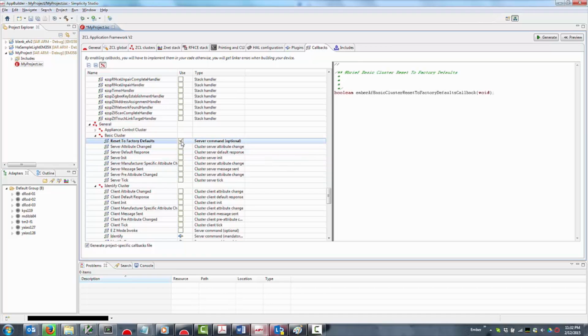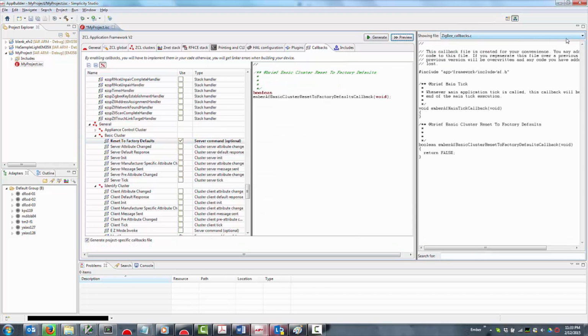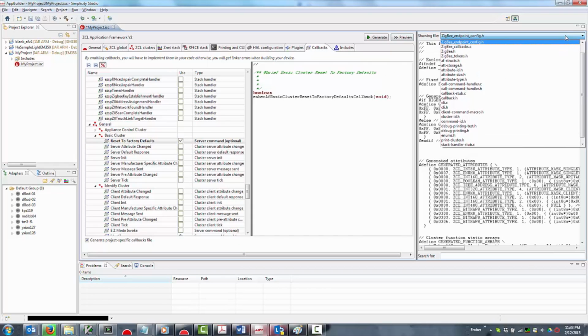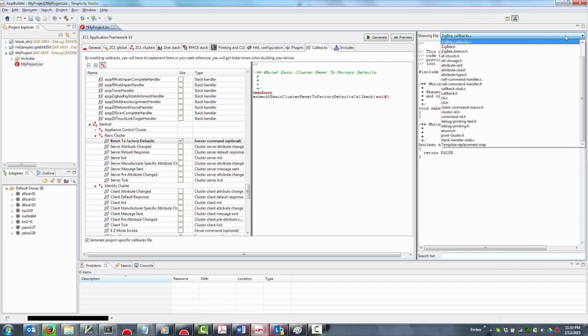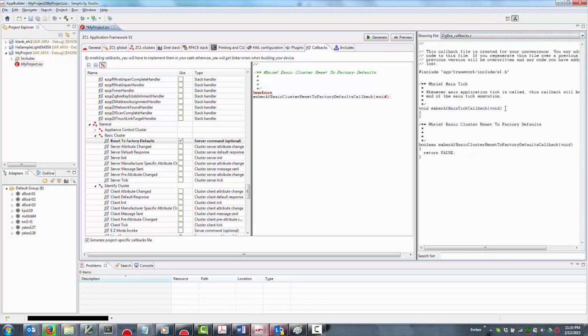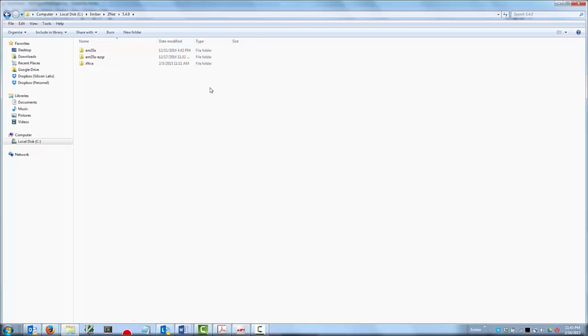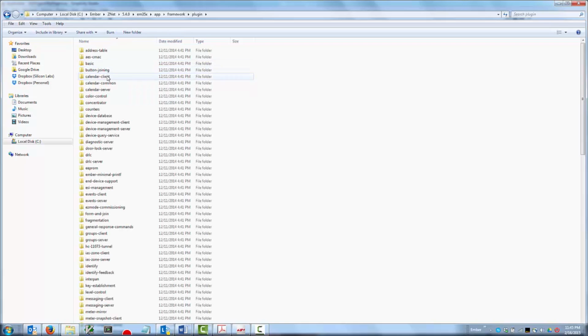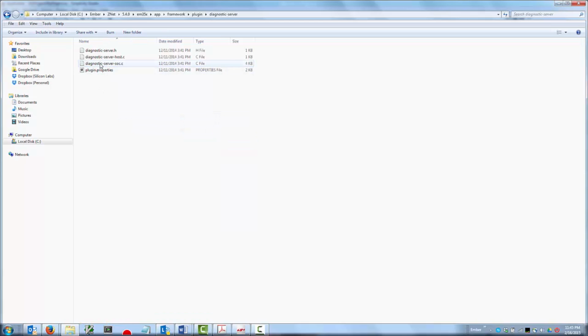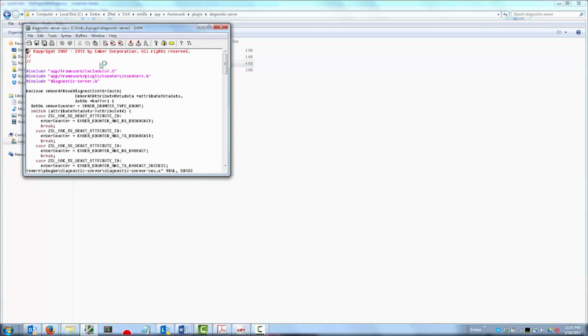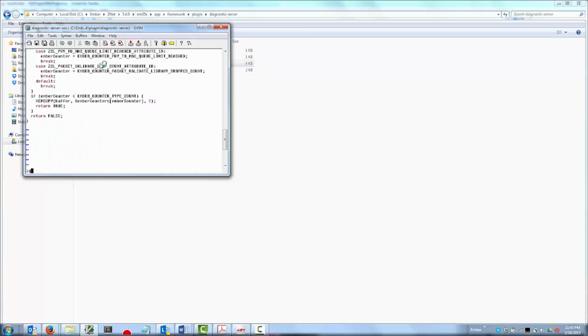Within the callback implementations, developers can utilize the entire HAL and stack APIs, as well as a complete set of application framework-specific APIs that often provide high-level application wrappers around complex HAL or stack functionality. These APIs are documented in the Application Framework API Guide and can be found in use in existing sample code, and, like all of our application framework, full source code in C is provided to help understand the implementation of these APIs. There are over 200 callbacks to choose from, plus the application builder automatically provides a unique callback for every incoming message type supported by your device's application protocol, so you can handle each incoming command frame exactly to your liking.